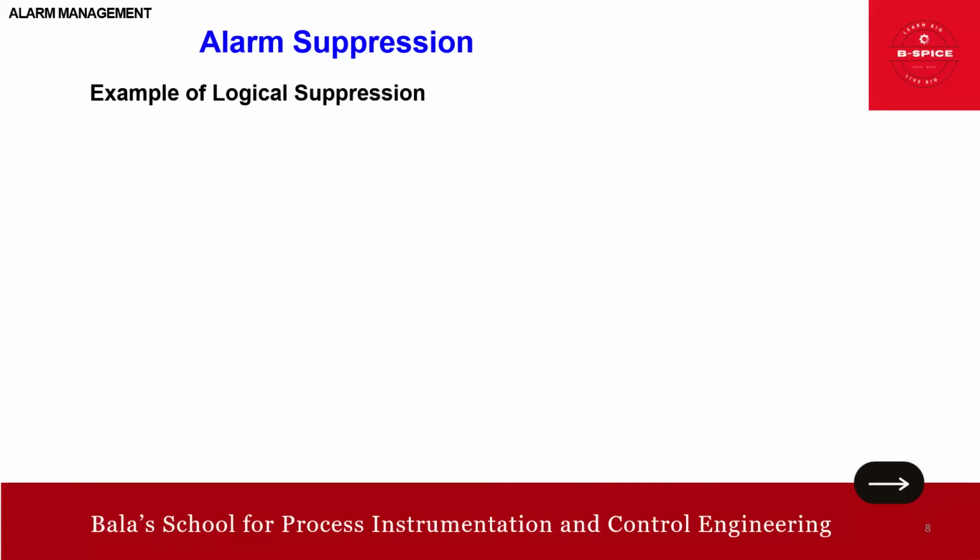Another point is LSLL, which trips the pump, should not normally be an alarm. If an alarm is justified, it can be suppressed on unit shutdown or when the pump has been stopped, the alarm has been present for 20 minutes, or tripped by a first failure device.